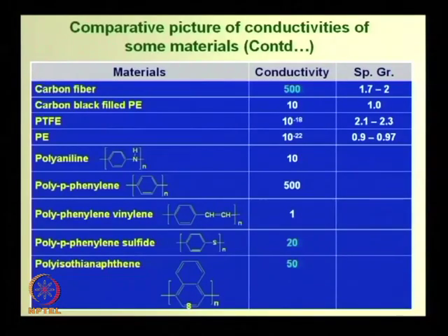Carbon black filled polyethylene conducting. Now, I told you a grade of carbon black, 3 grades I mentioned: thermal black, furnace black and channel black. Now, channel black is conducting in nature. Conducting in nature means it may not be very high conducting, but it shows some conductivity value.